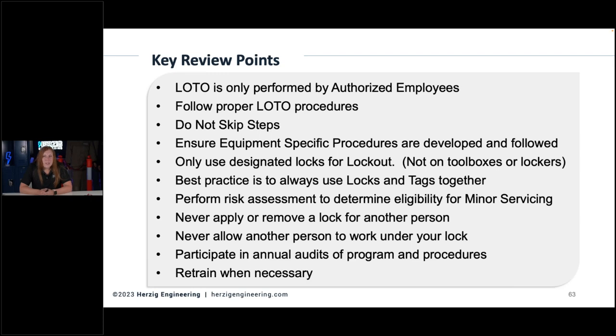Definitely need to perform risk assessments. Minor servicing is overused. People try to say, oh, well, we're going to set up this equipment before operation, and so we don't really need to lock it out because it's simple and routine, blah, blah, blah. It's like, okay, but you're still putting your body or your hands into the danger zone, so no, you do still need to lock it out.